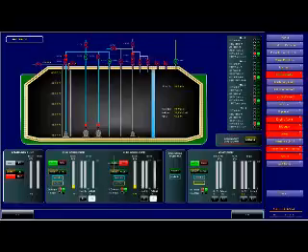Or you want to start that pump? Okay, start that pump on manual, put it on manual and start it. See what will happen. The pump is not starting because it has tripped on the low amperage. So cancel the low amperage alarm.